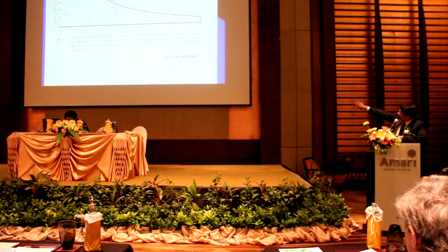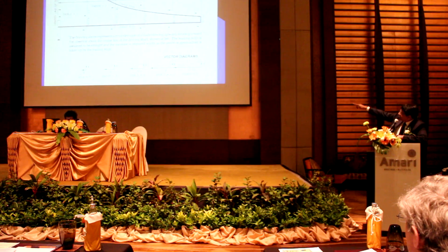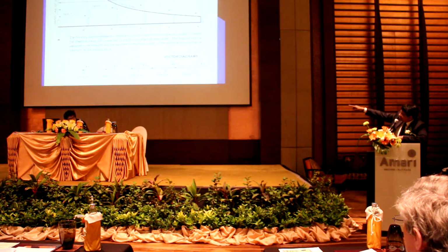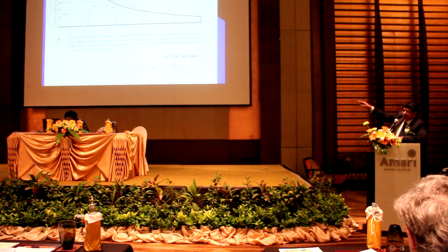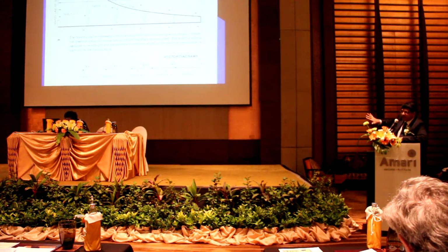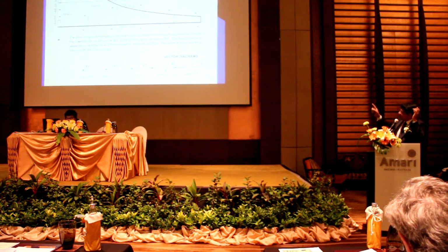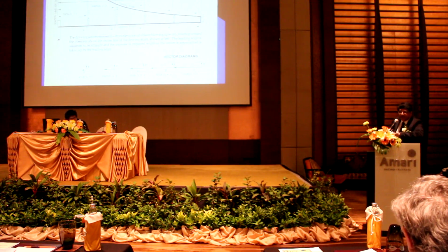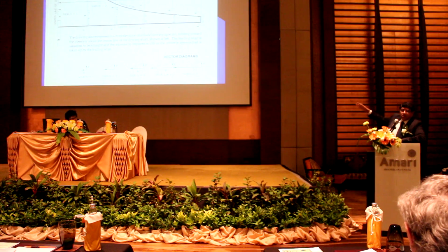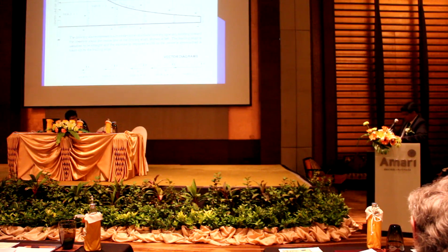As you can see in the right extreme triangle, it's a smaller angle, the dotted line making with the U, and there you can see it's a larger angle, which means the blade aerofoil has to be twisted. As there is a small blade which I brought along, you can see outside what I mean by this concept of needing a twist to maintain more or less uniform velocity.